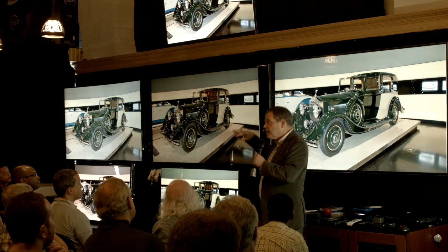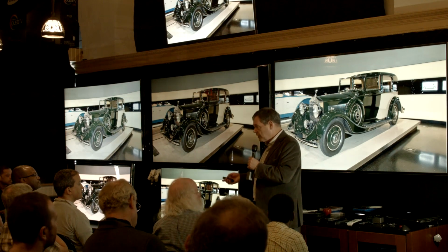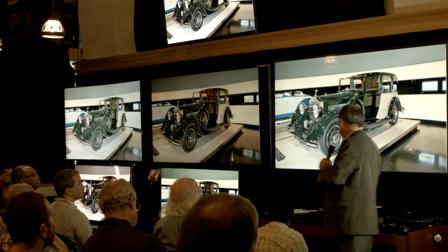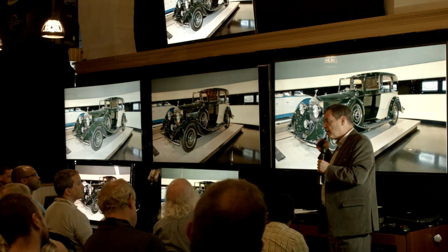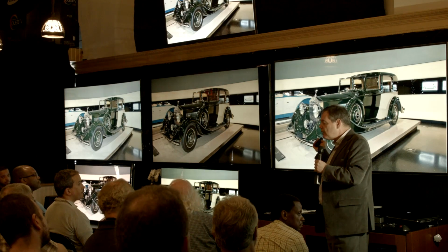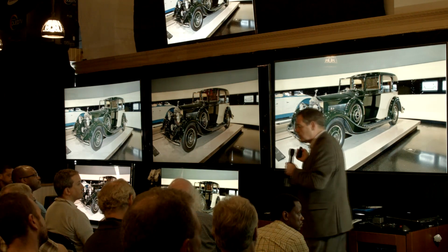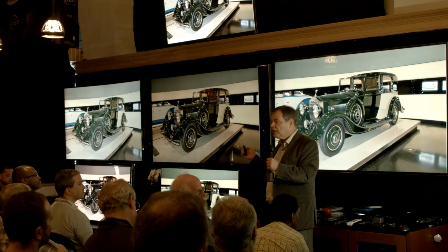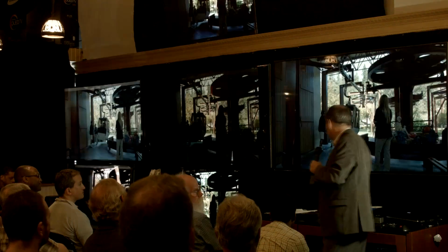In order to get high dynamic range, you do need a brighter set, but you also need the bit depth to drive it. So there are going to be real limitations on what high dynamic range is. Even with some of the latest backlight technologies that are being used with LCD, which are more efficient, there's still going to be limitations on what you can get out in light output.